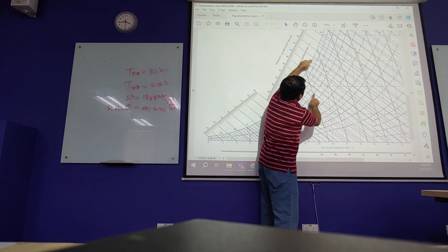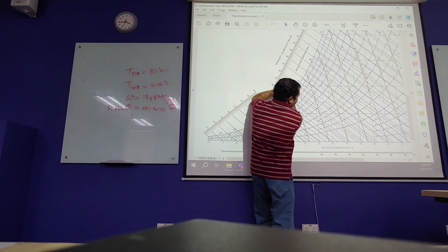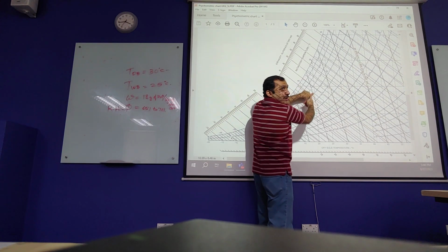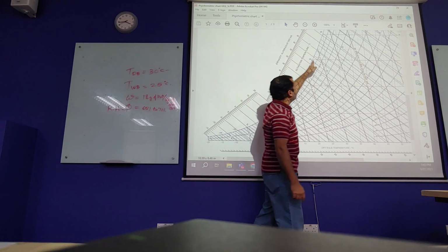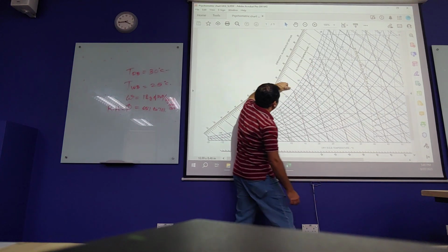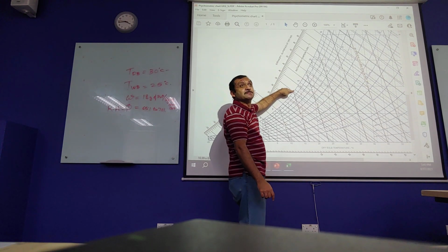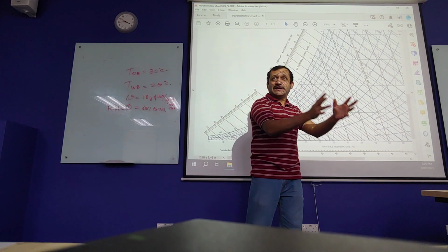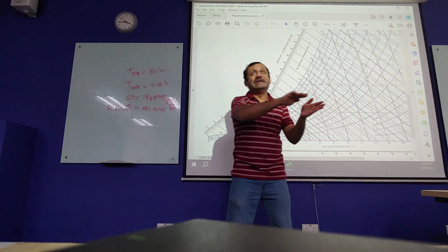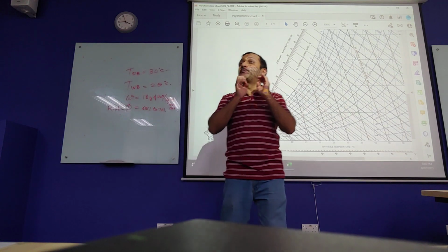So if you cool it down to that point and then heat it, we can go to 20 degrees, 60%. You cannot just cool it to 20, you have to cool it down to about 14 or 13 degrees Celsius. So you cool the air from 30 to 14 or 13 and then heat it to get to the right temperature, and that's so precise.